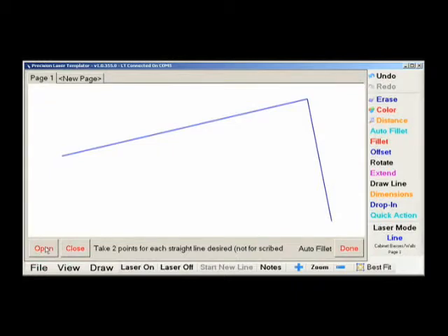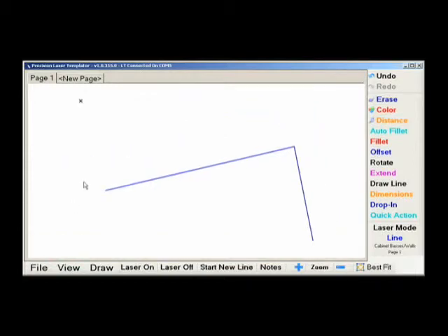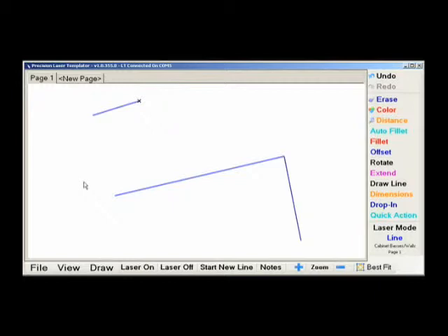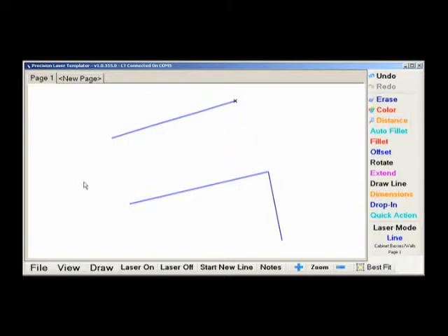The way you do this is use autofill to template the straight surfaces. Then click the Open button. Next, proceed to do the scribed walls at whatever interval you want the measurements to be taken at. One thing to remember is when you're taking measurements, you should keep the laser beam about 3 inches outside of the corner to avoid any reflection, or you should hit the laser beam directly in the corner.